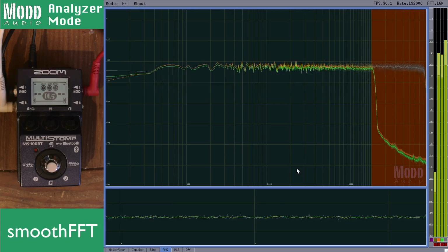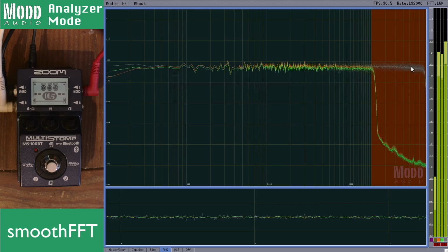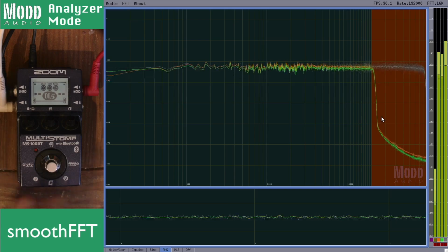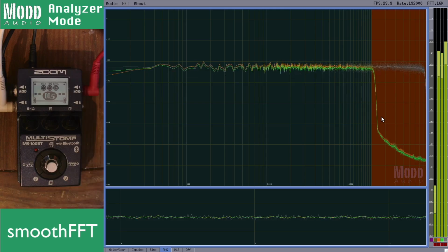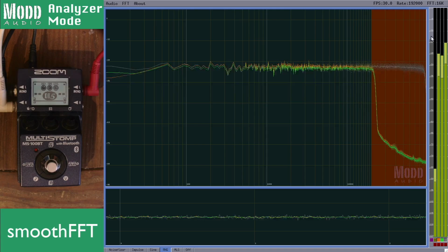It uses a random number generator to generate white noise. And you can see on this, the loopback channel itself goes all the way up to 96 kilohertz-ish, and then the Zoom itself only goes up to a little above 20 kilohertz because it samples at a slower sampling rate than the 192 kilohertz we're doing on the audio interface. But anyways, I'll take a look at this.